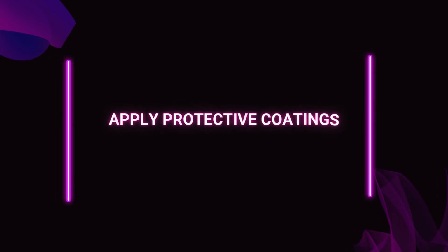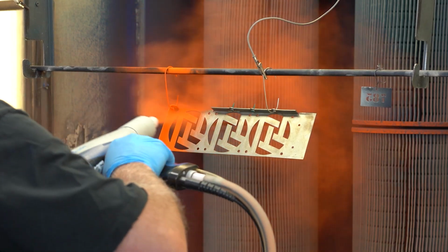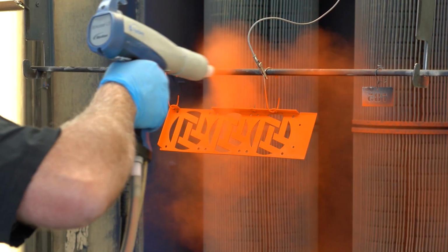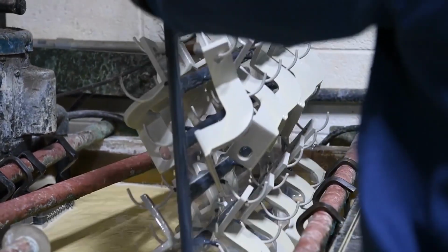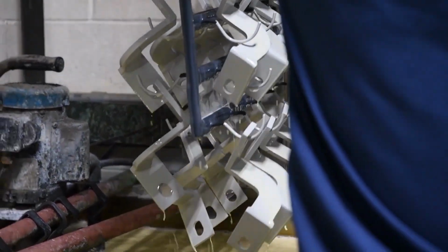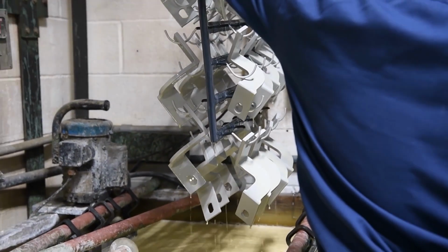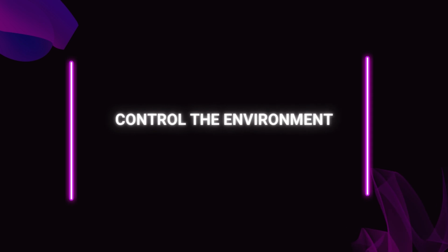Number 3, apply protective coatings. A coating like powder coat is an excellent insulator, and tin plating acts as a barrier against corrosion. This is a highly effective strategy, but with one critical rule. Keep in mind, if you only coat one of the two metals, coat the cathode, the more noble one. And 4, control the environment. Remember, no electrolyte means no corrosion.